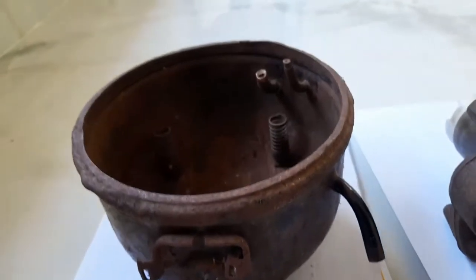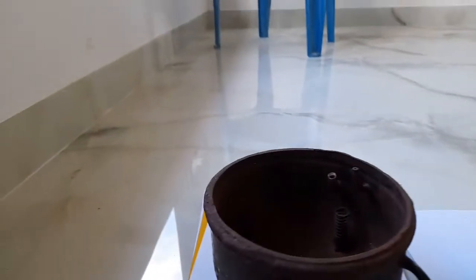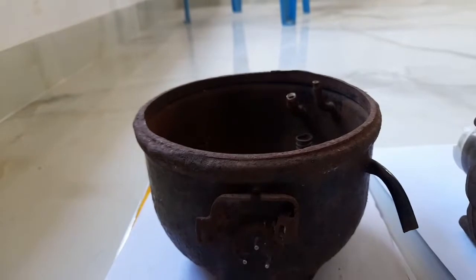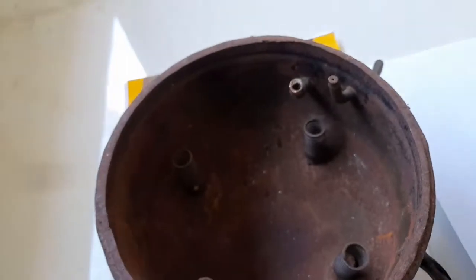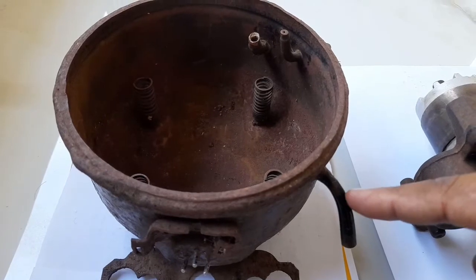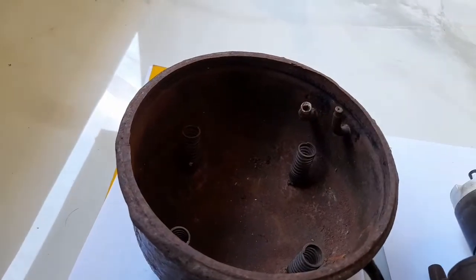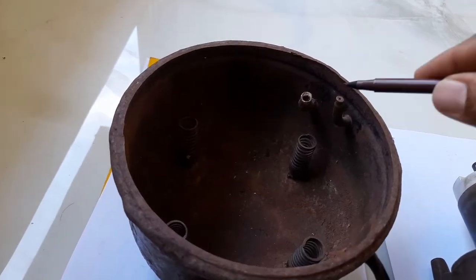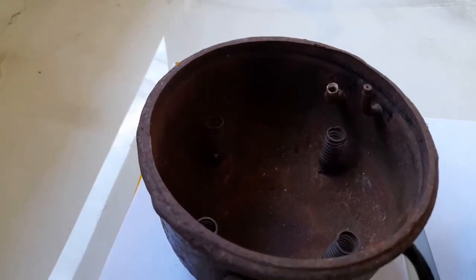Well friends, in this session we are going to learn about the practical parts of a hermetically sealed compressor. Well, this is the bottom shell of the hermetically sealed compressor. There is a top shell as well which fits over this, and this is provided with a suction line which is communicated to the evaporator, and then there is a discharge line, this line, which communicates with the condenser, and there is a charging line here through which charging of the refrigerant is done.